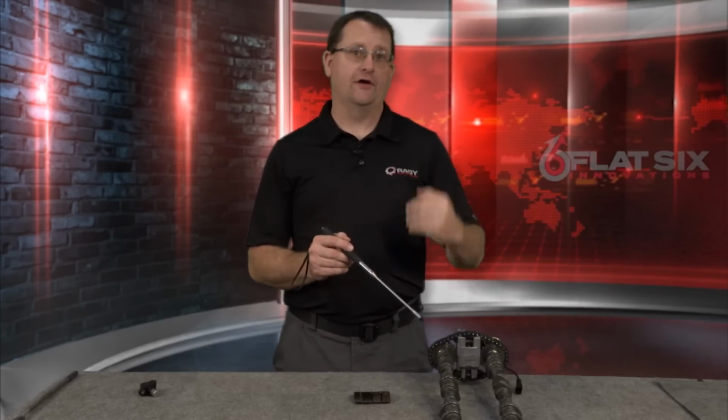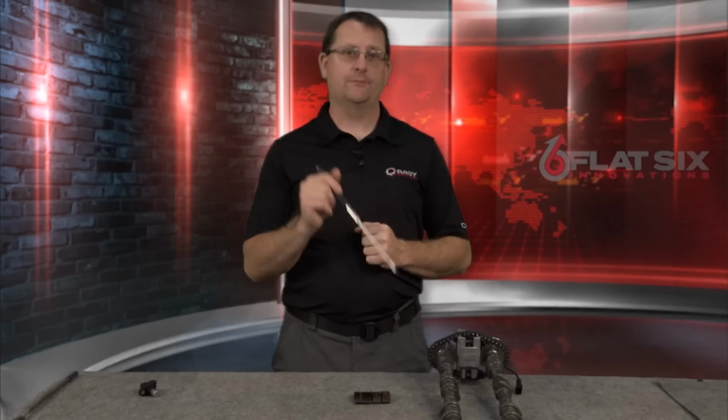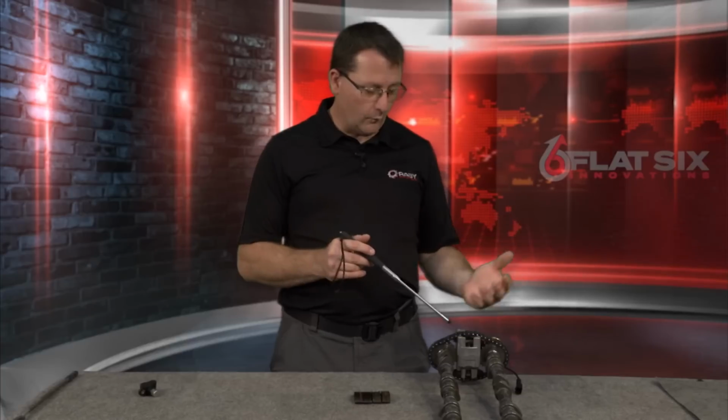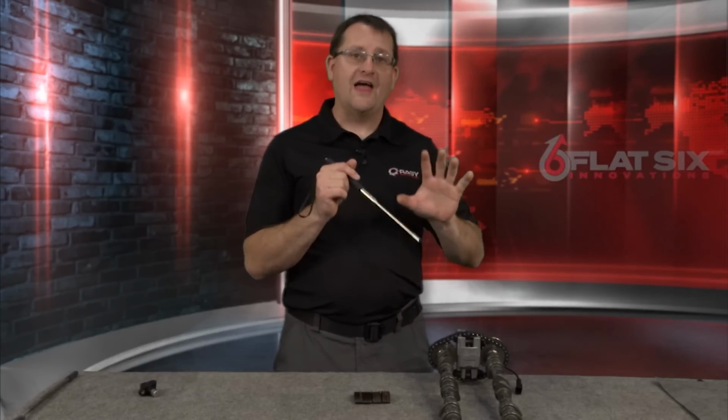We've seen engines that actually had holes in the head casting and let some of the oil bleed out of the casting and not even go into the chain adjuster unit. That one went to 4 different dealerships and 3 other shops with no diagnostic being performed correctly before we figured it out. So there's weird things that we see at our level that other people don't get to see. And that basically means there are no absolutes. So if you get the Durametric system and you're able to look at your camshaft deviations, don't worry that much about why is this happening, blah, blah, blah.